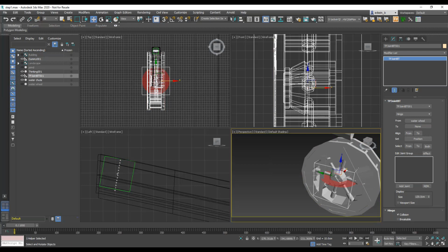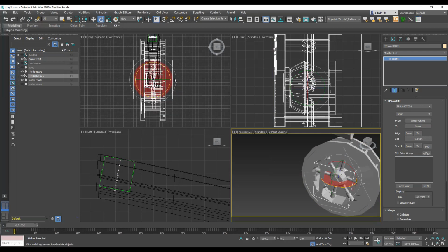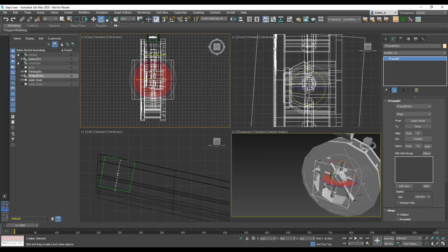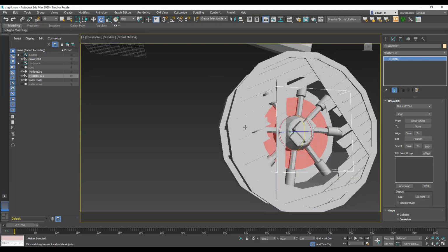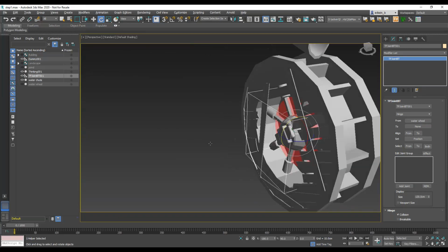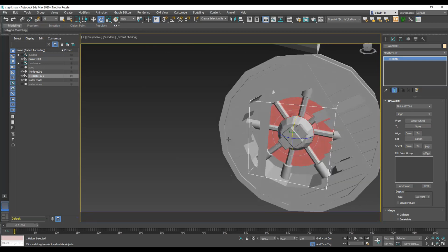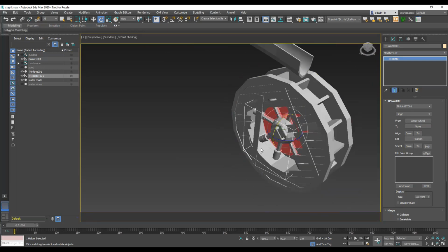The easiest and best option is to just grab the joint and rotate the joint by 90 degrees. Let's be accurate, or this will start wobbling. Now, as you can see, our disk, our visualization of the hinge, is exactly aligning with the rotational direction I want to have for my object.